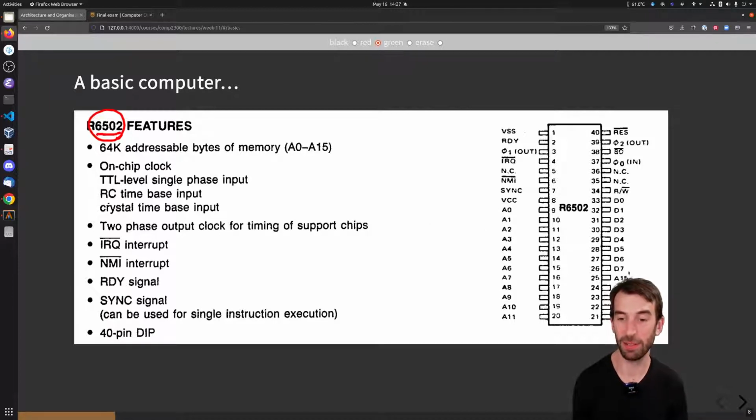It's an 8-bit CPU, so the register is only 8 bits on this CPU, and when it accesses memory, it takes 8 bits at a time, not a full word or 32 bits of memory. A word on this is 8 bits, not 32 bits like on your microbit. On this CPU, there's the data bus, so that's for reading and writing to memory. Getting in and out, you get 1 byte at a time, D0 to D7, all the data pins. So each of those little pins would connect to a pin on a memory chip, which would be part of its memory.